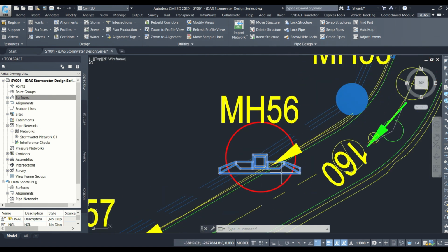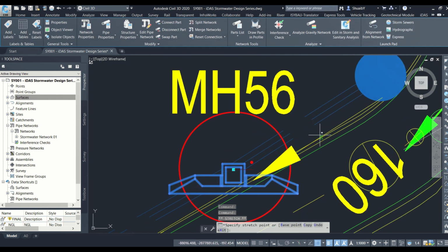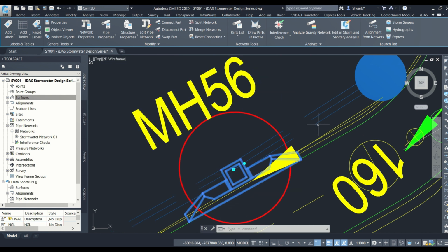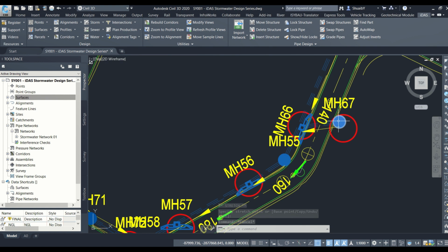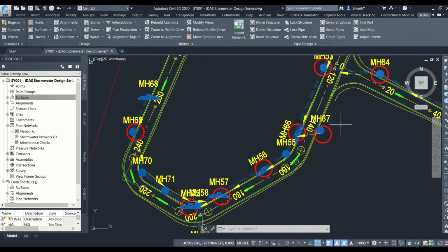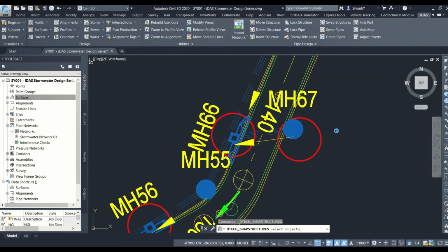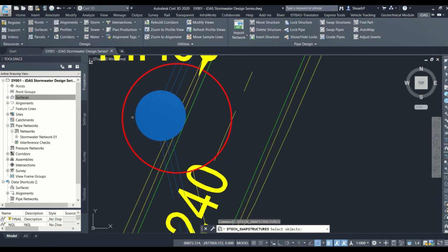All right. So let's go in here. Let's position this really nicely along the road, maybe neatly along the road edge. You can see this is good. So we've got all of these things that are tapping in there. You can see even the offset, the reason why you have an offset, because I did the offset alignments, if you remember or you recall, and this is why it fits in really good. All right, so I'm going to change that one to a curb inlet as well. These are all low points, normal low point curb inlets. I'm going to change that one as well. Let it go.